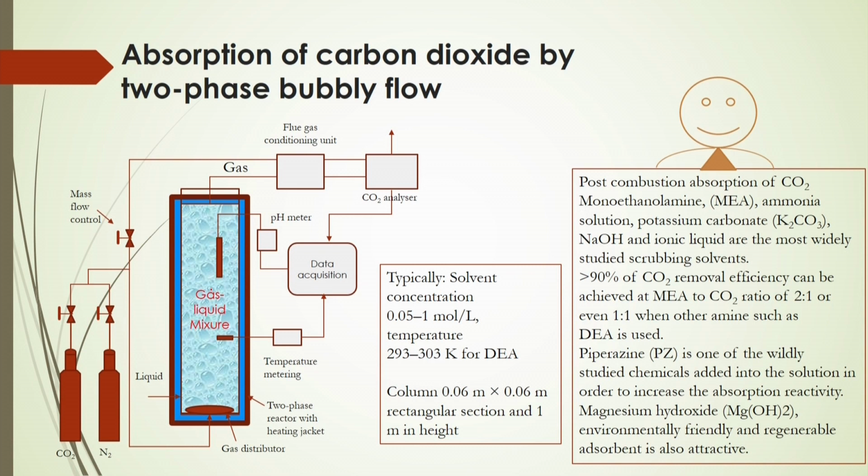Now, the question is why should you make bubbles, when you could just supply the carbon dioxide gas in a column in the central region from the bottom, and supply the liquid from the top of the column, which is called a wetted column? You can also get surface area, but the surface area will not be enough to get more mass transfer compared to this bubbling system.